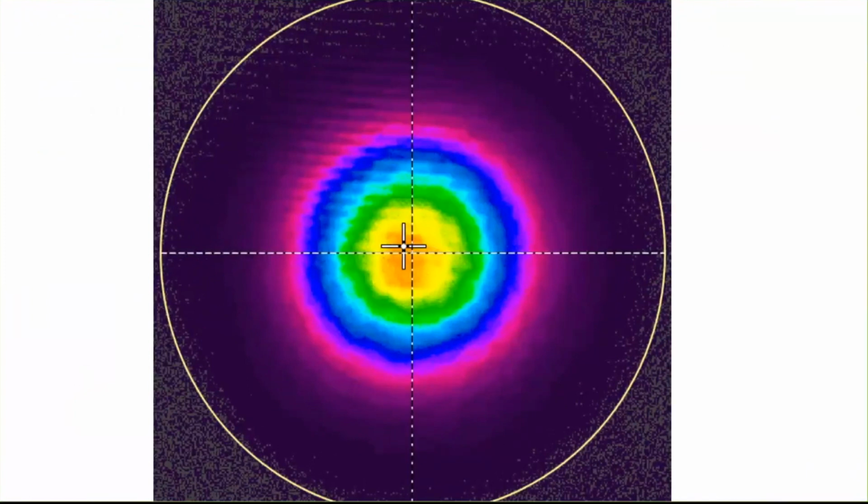And in this beam, we have the centroid enabled. That's the dashed lines that intersect. That is the cursor feature. You can actually grab that and move that around, or set it to automatically track peak or centroid. The smaller reticle is the crosshair feature. And we give two different options for being able to track those positions depending on preference, and when they're both enabled, there are also some results where you can do linear measurement between the 2 points.